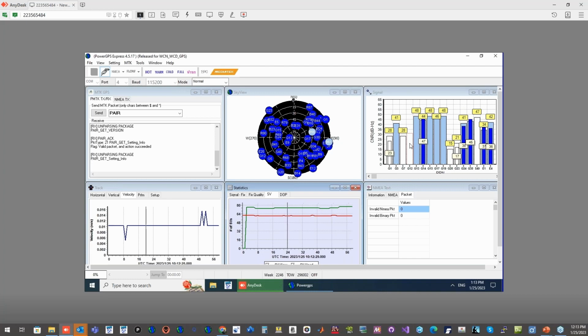For example, we talked about the GPS basics, so we will not take all the satellites into the calculation. Maybe some of the satellites are wrong or have an issue, and then we cannot trust them during use and calculation, because if we want to have 1 meter accuracy, they will give us 5 meter accuracy because they have issues in the transmission of the information from the sky to the Earth. So this is the reason that you see a few satellites with color and a few satellites blank.